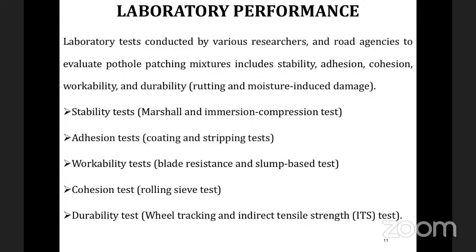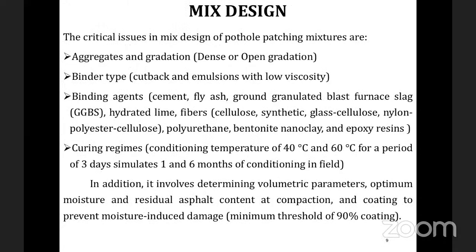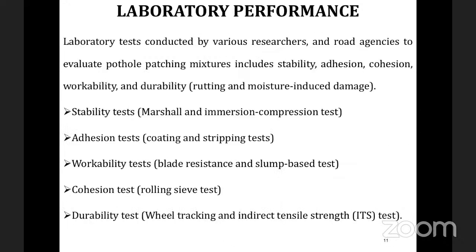Coating may be assessed by the boiling test, stripping test, Nicholas stripping test. There are a lot of tests. In addition, nowadays they are also using techniques like image processing in order to assess the coating percentage. As I told here, 90% coating is the threshold coating percentage. So image processing is one of the new techniques which we can work out in order to assess the adhesion.